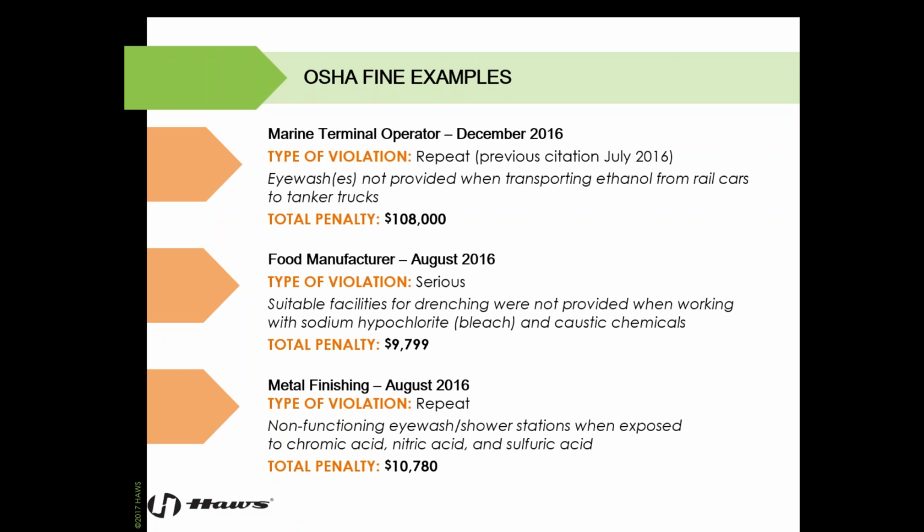They did have emergency eye washes and showers, but OSHA will come in and inspect those pieces of equipment to the most recent ANSI standard, and they were non-functioning. That could mean a lot of different things. Again, the flow could be too low, could be too high, there could have been non-tepid water, a lot of different potential instances, and that total penalty was around $11,000.